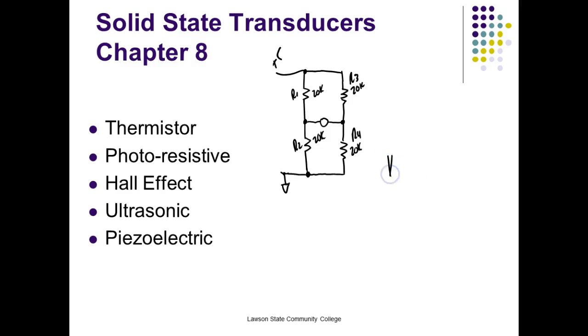So the voltage divider formula says VR2 would be equal to the size of the resistor divided by the total resistance. And of course, the K cancels, the 0 would cancel. So that's 2/4, which means this resistor right here would drop exactly 1/2 the voltage. Of course, we knew that because it's a series circuit, right?